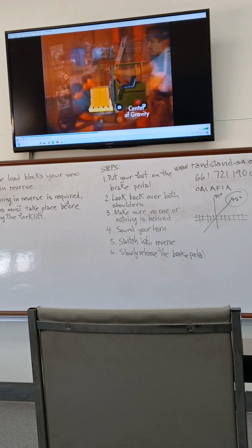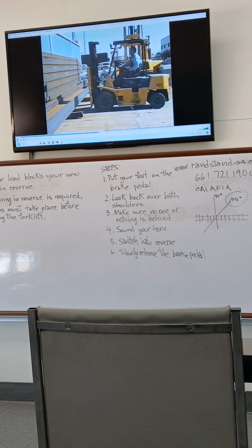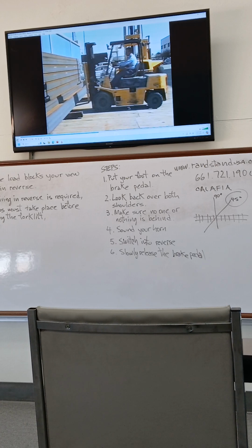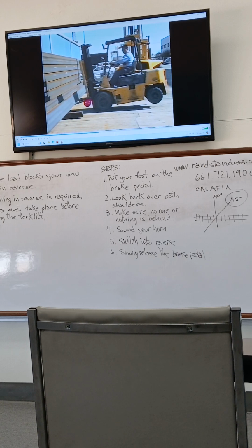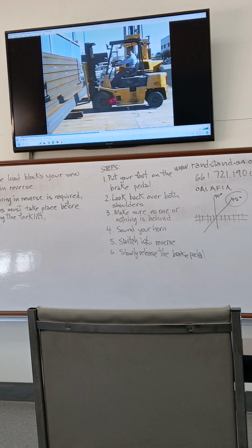Forklift engineers designed the forklift with this in mind and calculated the center of gravity shift in determining the safe lifting capacities. When equipment operators exceed the safe lifting capacity and try to lift excessive loads, or if they have extended load centers and try to lift heavier loads, the center of gravity can be exceeded and the forklift will tip over towards the load.